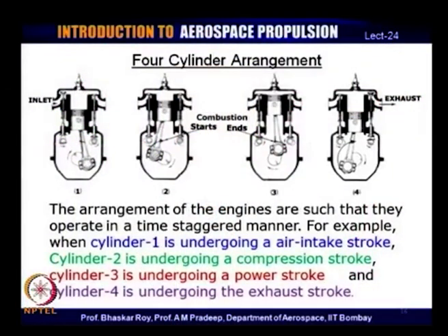It is entirely possible that if you have a 4 cylinder arrangement, each of these cylinders could be operating in a time staggered manner that I mentioned earlier. Let us say the first cylinder could be undergoing an air intake stroke, the second cylinder at the same instant could be undergoing a compression stroke, the third cylinder could be undergoing a power stroke, and the fourth cylinder would be undergoing the exhaust stroke.